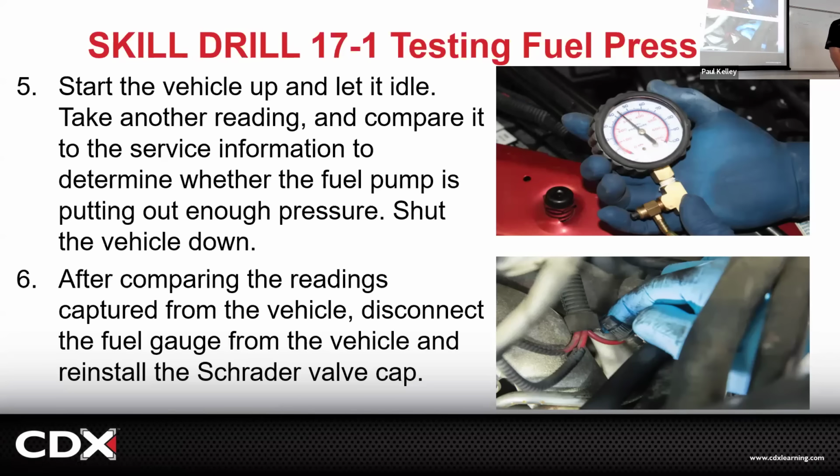There's been times where I squeeze this little button and this drain hose, just a little bit of fuel comes out and I'm like, that's not a lot of volume. It's a lot of pressure, but not a lot of volume. When I squeeze this, it should fill that Gatorade bottle within a few seconds. It should be quick, right? So I'm just testing the pump thoroughly, right?